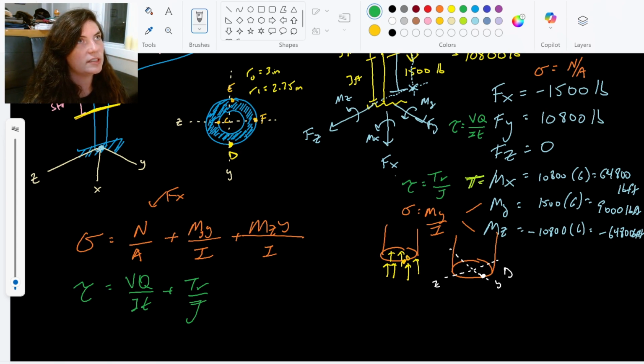So what that looks like is I have compressive stress on one side that goes to 0 at the centroid, and then it goes to tension on the other side, all humping over that y-axis, like a little dolphin coming out of the water and going back in, right over that centroidal y-axis.